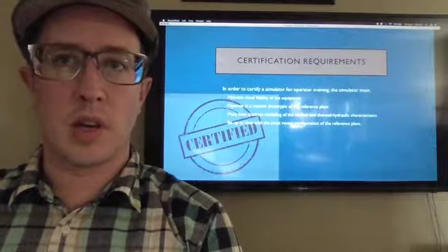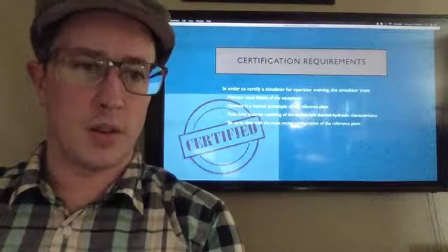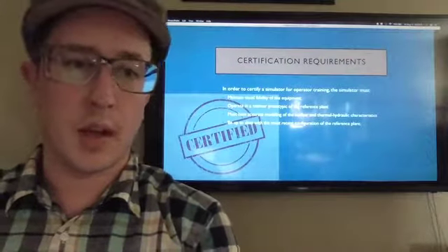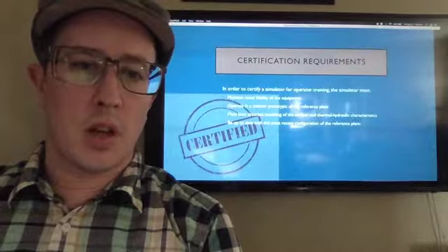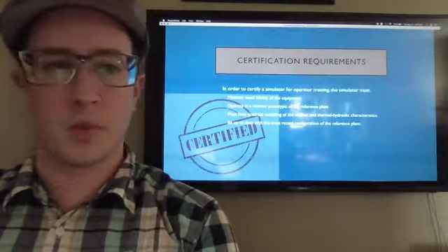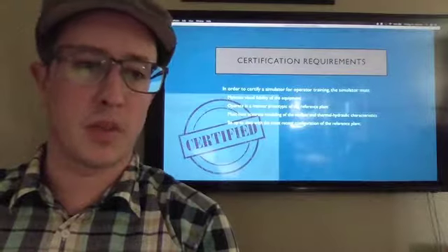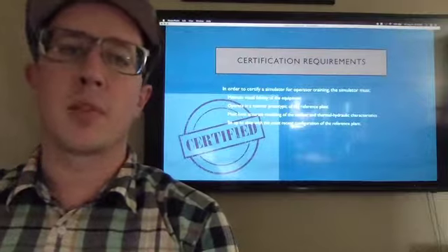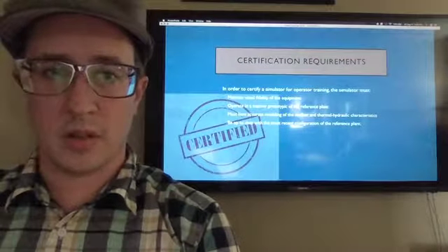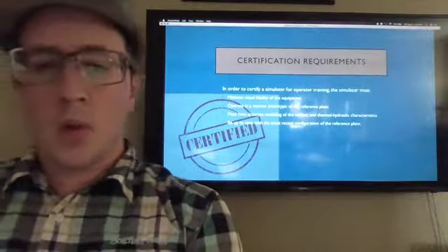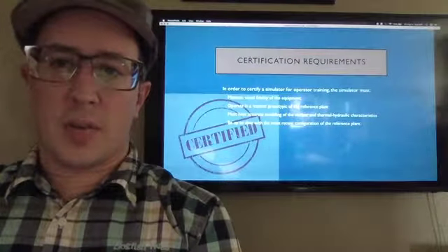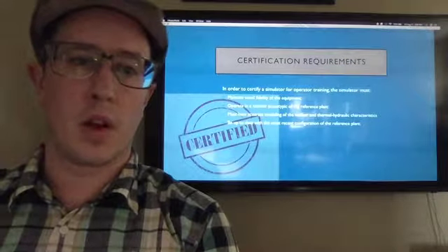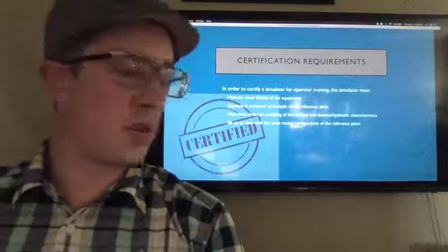So in other words, as heat is added, you see the associated temperature rise and cooling effects, and so on. But most importantly, and the one that is often most difficult, is it must remain prototypic of the plant. So if there's some sort of field change that is installed on the plant, this must also be reflected in the simulator itself, which does provide for training operators on new equipment as it's being developed, but it also means that they're training on the most prototypic device.